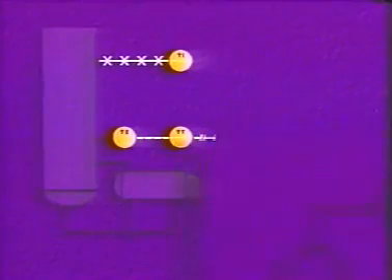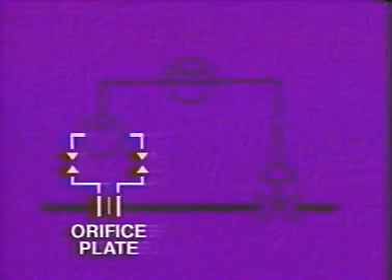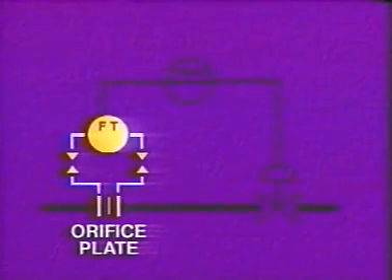To review, here is a complete control loop depicted by instrument symbols. The primary element is an orifice plate. This is shown by the 3 lines that interrupt the solid line for piping in the lower left of the drawing. 2 pressure taps connect the piping with a differential pressure transmitter, which is marked FT for flow transmitter.